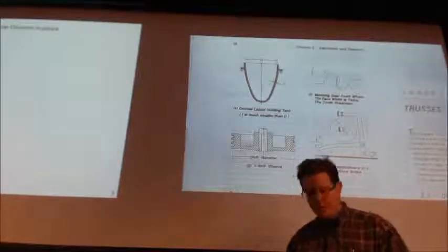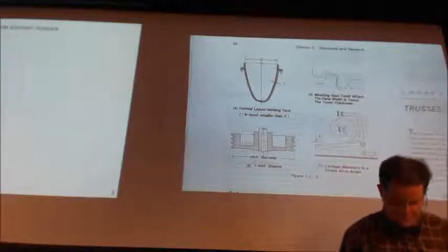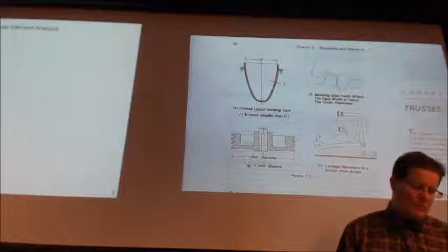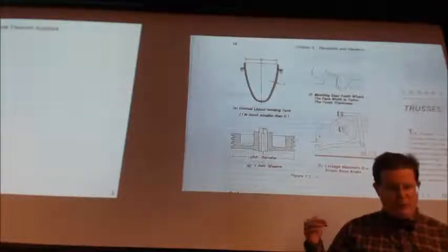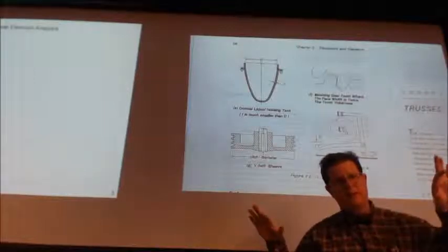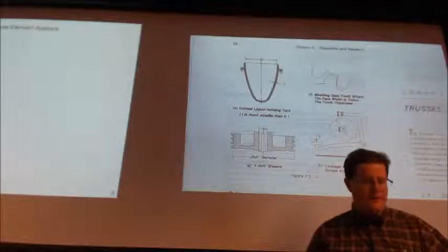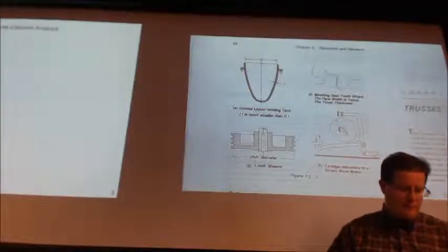Three-dimensional solid. Three-dimensional solid would be one way, you bet. If you treat the root of it as solid, then you can treat the tooth as a beam, right? May not be the best approximation, but it's feasible.